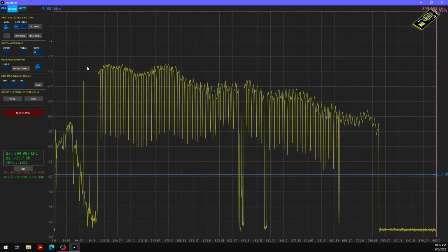Because there's amplifiers that are only boosting what's going back to the cable node or back to the cable company, I'm not going to see so much upstream data because a lot of that is not being amplified in my direction. But I am seeing all of the downstream usage because that's being amplified towards all the customers.